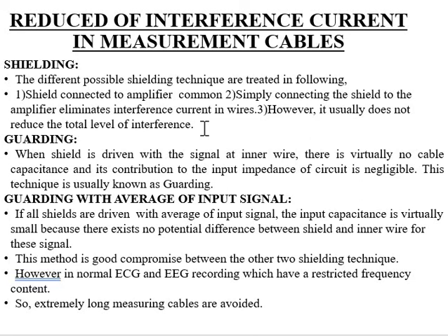So extremely long measurement cables are avoided. Finally, the conclusion is to avoid lengthy measuring cables. Try to make the length less than 1 meter.